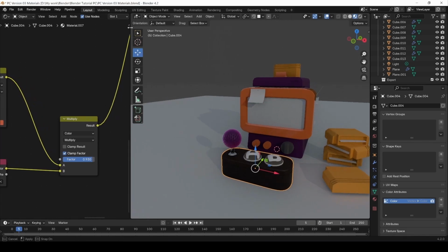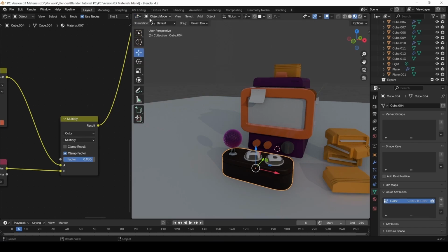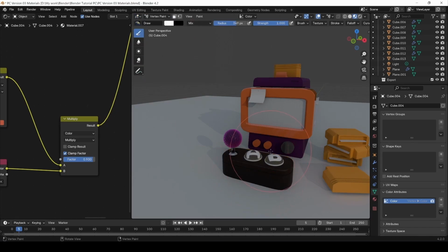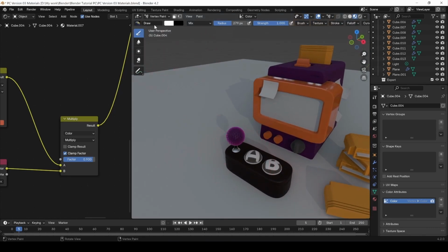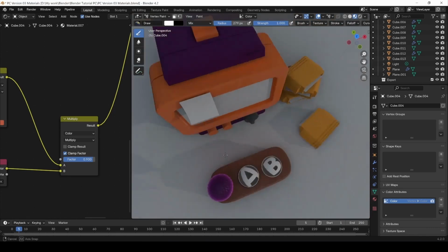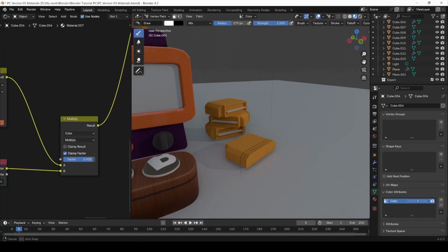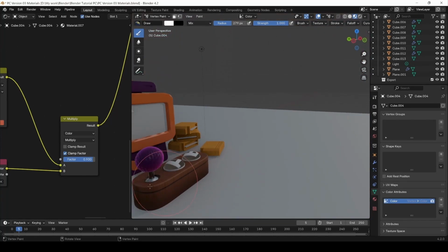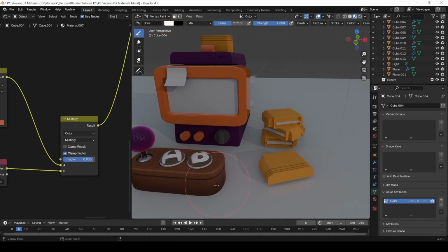And now, if you do this, and you go here to 3D viewport, and you go here to vertex paint, you can actually do this. Like you can take it as it is, and just with the white color selected, and you just color. Let's get our colors back. Let's get it as it was because we already added the gradient, so I don't have to make the bottom shadowy. But if you press Ctrl, you can color with black, and you can change the strength.